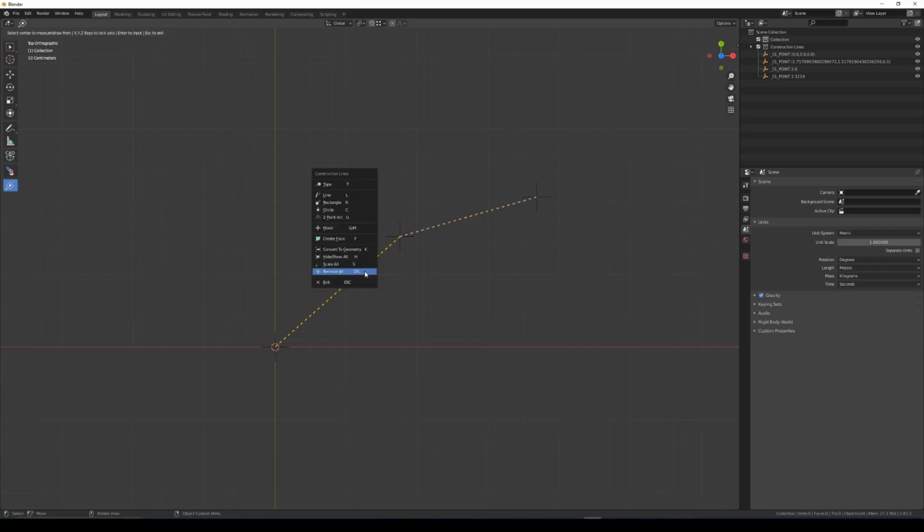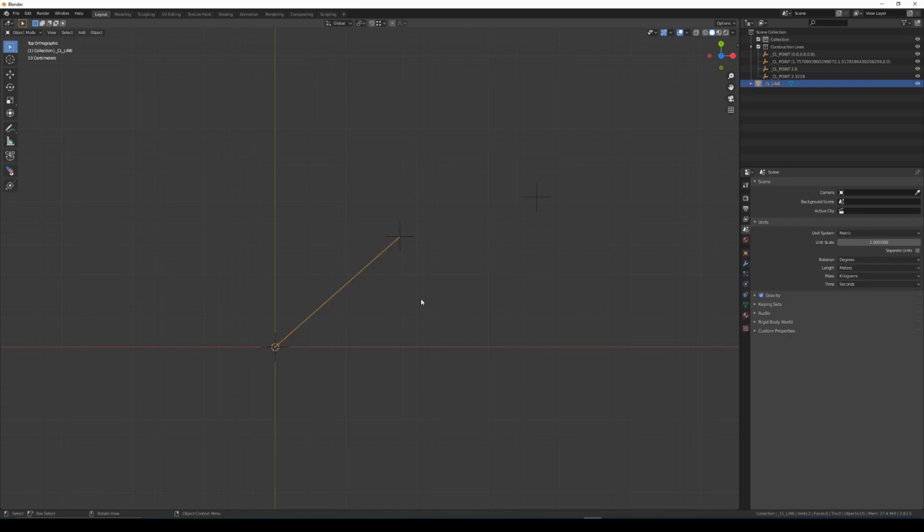So I've now added this ability to shift and click and select a guide edge, which will turn it to an orange color. You can select multiple edges, and you can deselect in just the same way. And if you right click and select the new item, which is convert to geometry, or press the K key, that will convert that guide edge into a real piece of geometry so that you can use it outside in Blender. So you could snap to that with Blender's own snap tools, or just use that as a piece of normal geometry. So that's a new feature.